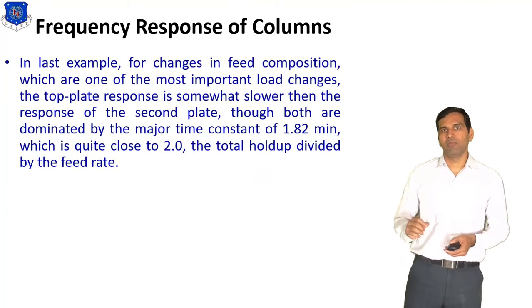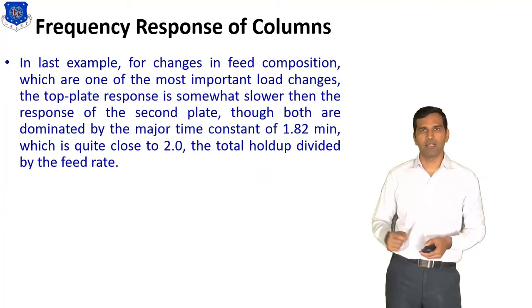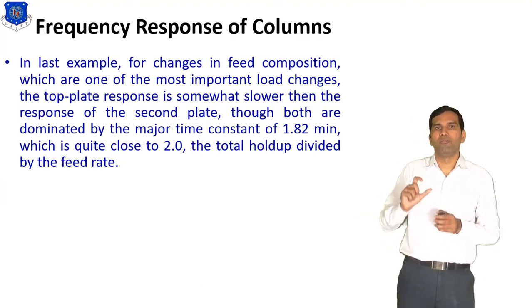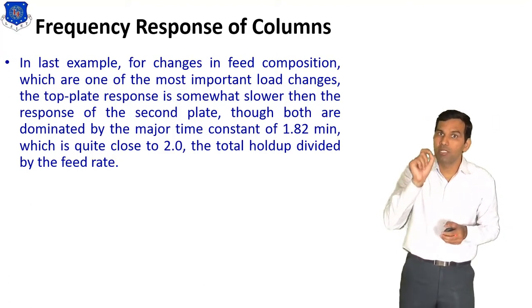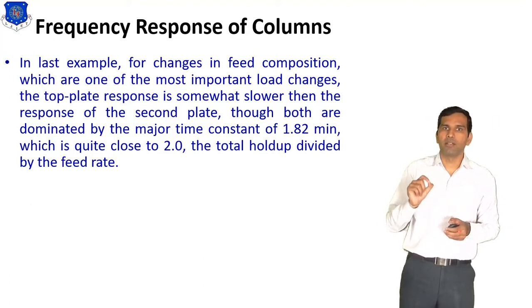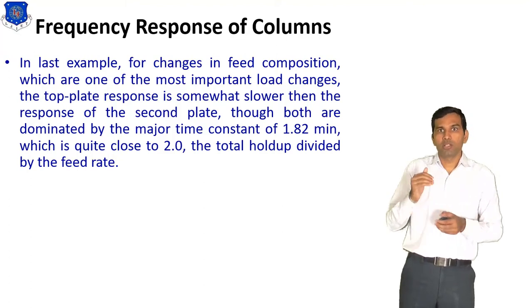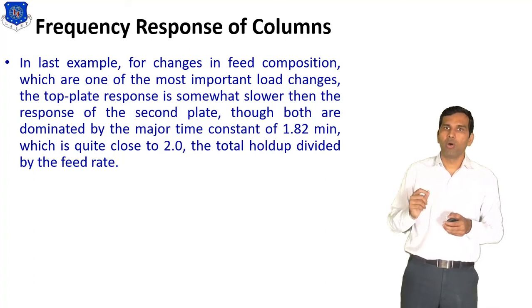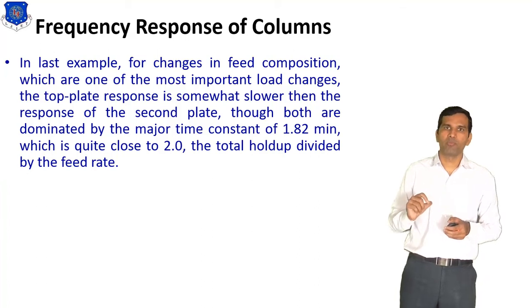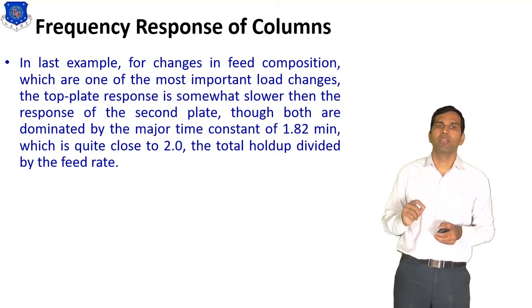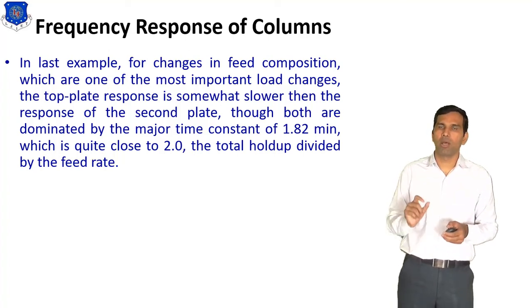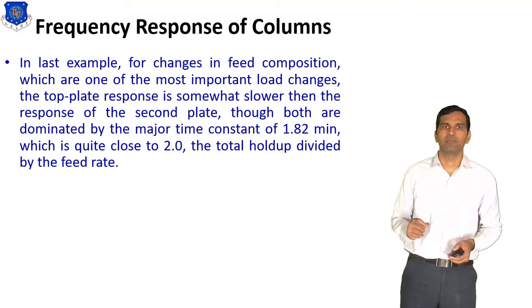The last example we discussed in my previous slide is the change in feed composition, which is one of the most important load changes. The top plate response is somewhat slower than the response of the second plate, though both are dominated by the major time constant of 1.82 minutes, which is quite close to 2.0, the total boilup divided by the feed rate.